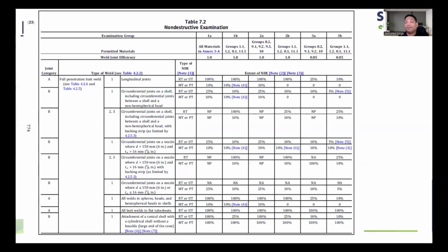We anyway perform PT before doing RT, that is the normal practice, but that requirement of 10% is not mandatory there. Here it is given, so you have to document the PT requirement properly. That is kind of additional which you will have.